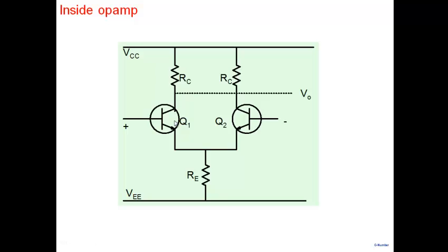In some other person's op-amp, it may happen that the beta of Q2 is larger than the beta of Q1. Therefore, the mismatches, by their inherent nature, vary from op-amp to op-amp, and that's why the results will be different. Some of you may measure plus 11 volt, and some of you may measure minus 11 volt. It's quite possible. Okay, so the source of that voltage is what we call mismatch, the result of mismatches inside it.